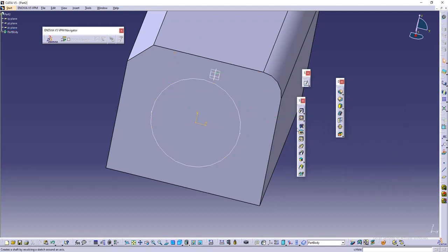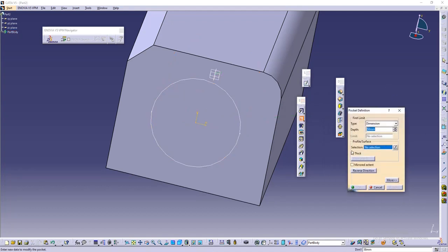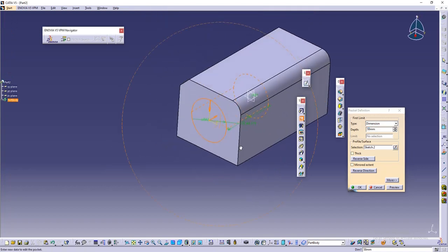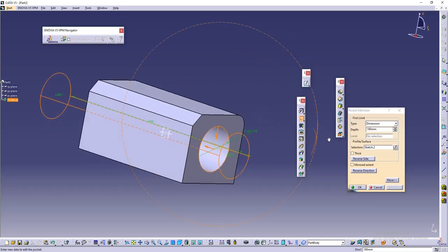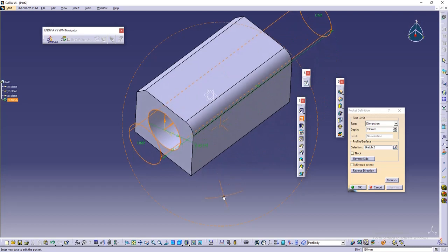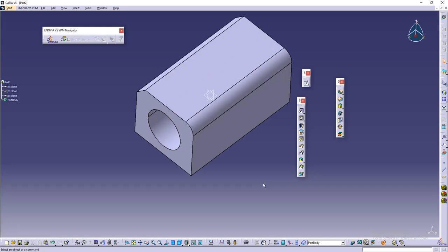If you deselect it, or maybe if you want to select this surface or the sketch option is open, I'll select down this profile, and now it is showing this much cut is available. So now again, you can see the same options for the pad and the same options for the cut or the pocket option, limit 1 and limit 2 is on, right? So you can just extend your limits here, and now you can see preview, it will show how the cut is operated, right? And now you can click on the OK button.